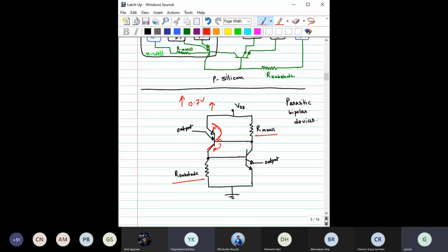These two terminals are already reverse biased, right? So what we have to do is momentarily, for some time, forward bias this. If we are able to forward bias this region, then what will happen to the collector current, say IC1? IC1 will increase. If IC1 increases, what will happen to this IE1? IE1 will also increase.